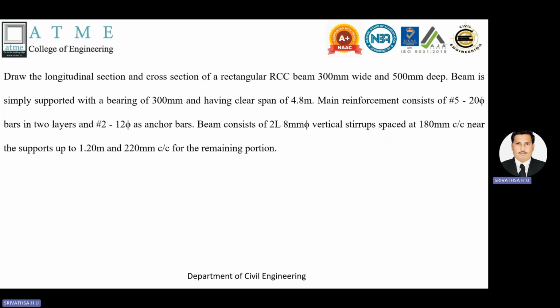Beam consists of two-legged 8 mm dia vertical stirrups spaced at 180 mm center to center near the face of the support up to a length of 1.2 meters and 220 mm center to center for the remaining portion.